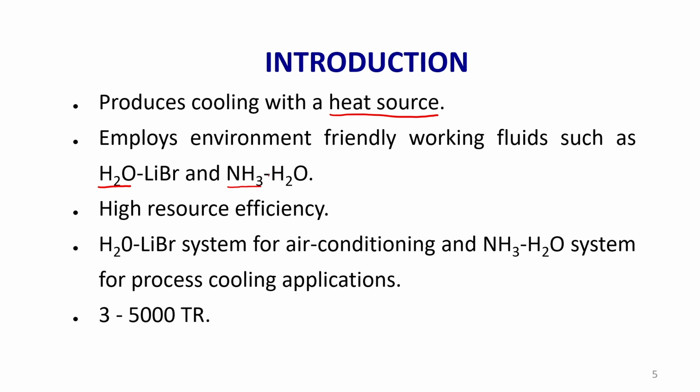In our country, whenever we represent the working fluid of an absorption system, first we write the refrigerant, the second component is the absorbent, A-B-S-O-R-B-E-N-T. Because in a vapor absorption system, the working fluid is a mixture of two, a refrigerant and an absorbent, unlike a vapor compression system. In a vapor compression system, if you take CFC, HCFC or HFC refrigerants, they are all single component. Of course, if you use azeotropic or zeotropic mixtures, there we have two or more refrigerants.